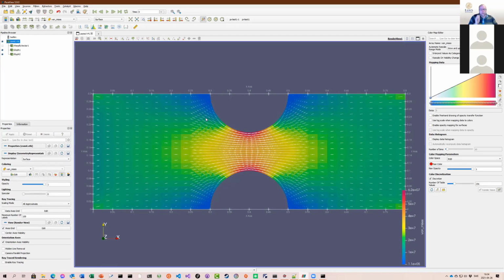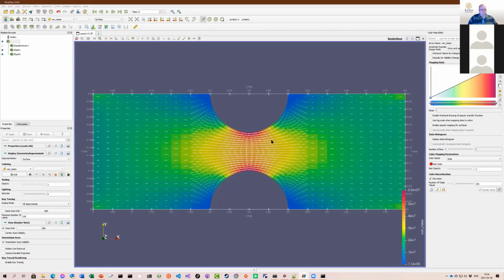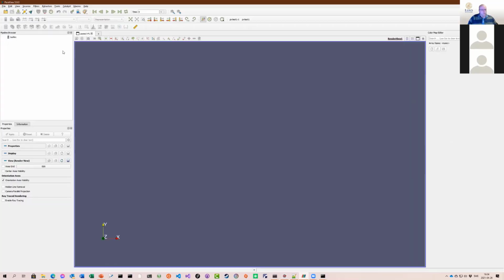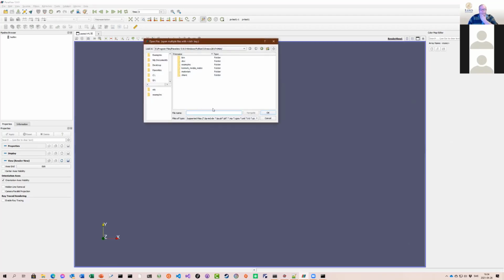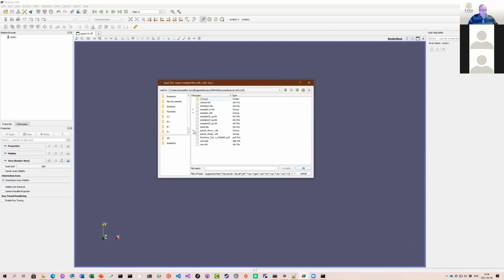So that was this, for those doing a temperature problem, I will show how this can be done as well. So now we do a reset here. Another thing that we will be using when you are doing the parameter study is that ParaView can handle it: if you name your files with a number in them, you can load them as a sequence.